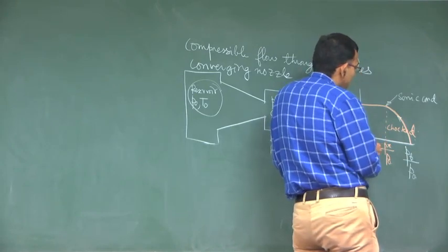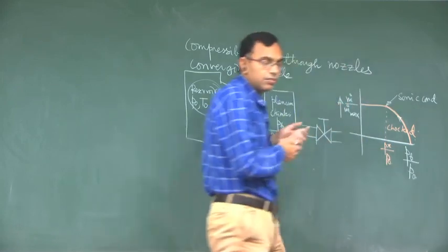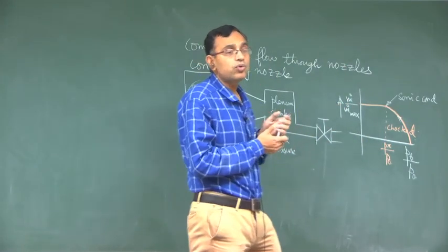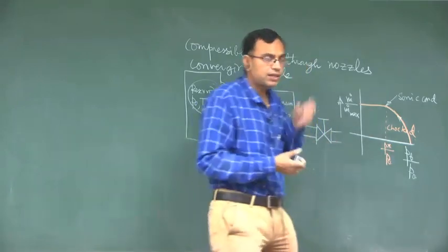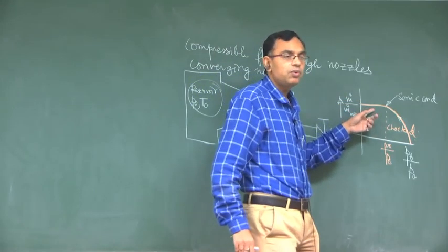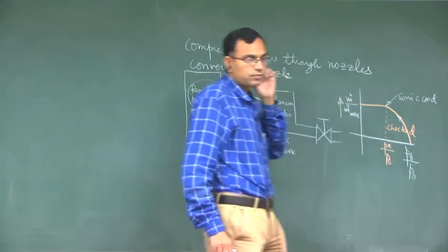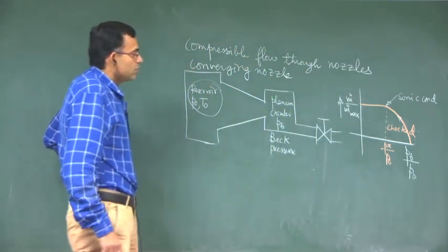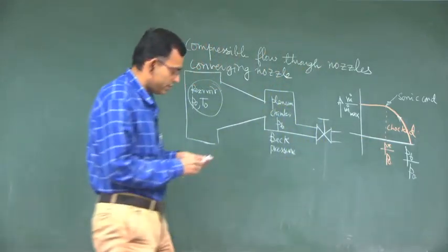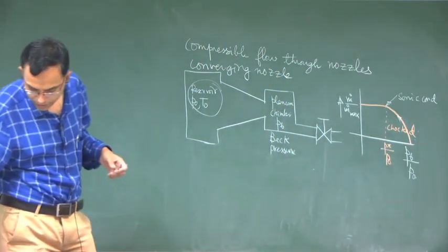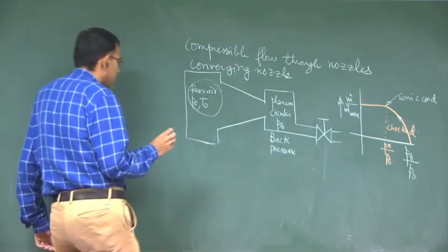With a reduction of back pressure, if you could somehow increase the mass flow rate, then you could increase the Mach number in the process, but that you are failing here, you are able to reach only up to Mach number equal to 1. So, that condition is P star. So, what is that m dot maximum? Let us calculate that and we will get something very interesting.